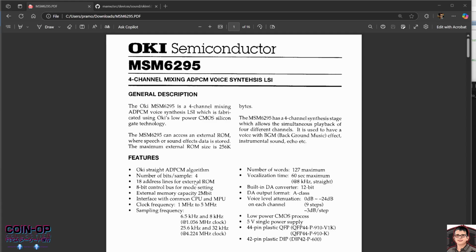In order to achieve cycle accuracy to the system that you're trying to do, you have to slow certain bits of logic down. We call this gating the clock. So you want to gate the clock in a certain way.